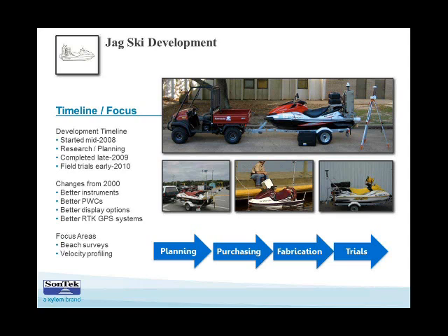Got another question about how shallow can you measure with the Jet Ski system? Well, actually, we mount our ADCP pretty low in the water to make sure that it's always below the hull. We're not surveying at fast speed. We're always trying to survey at about a meter per second or 2 meters per second vessel speed or less, just to get quality measurements. And so as a result, bubbles really aren't a problem off the hull.